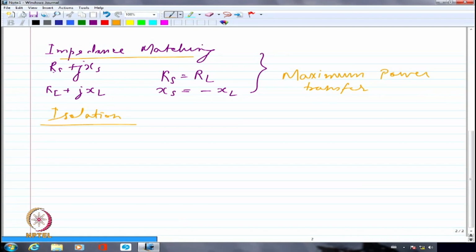That base drive will be at 15 volts level or even less, whereas the motor may be operated at even 1 kilovolt level. So I might like to have isolation between the motor and the transistor base drive circuit. That can be done very nicely by using a transformer.